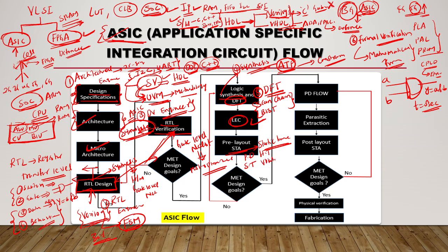What are these violations if setup time and hold time are not met? And clock skew and clock jitter. All those things you will learn in this pre-layout STA. And next, it is there in post-layout STA. If the design is met, it will go to the next step, and if the design is not met, it will go back to the initial state. For this you need STA engineers, separate static timing analysis engineers. And next, PD flow.